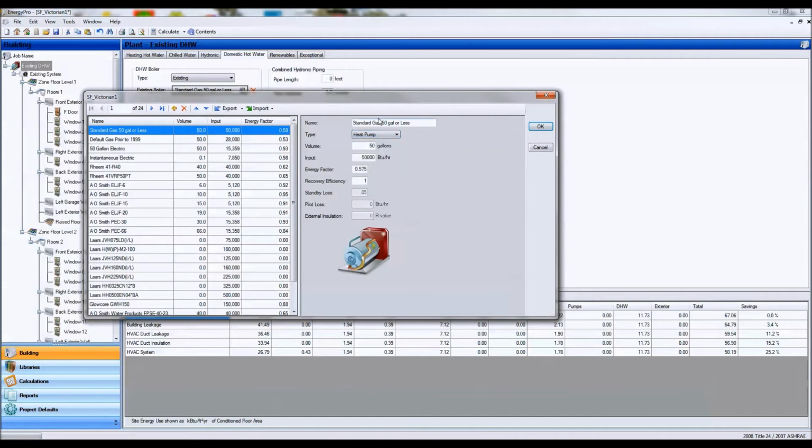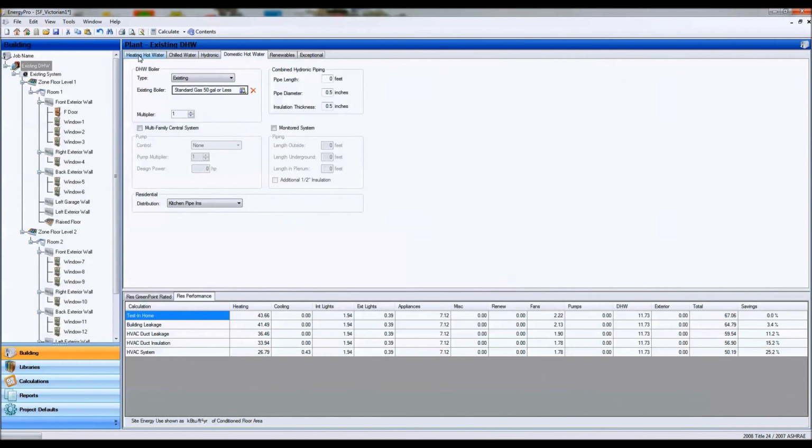And your heat pump water heaters, if you do have one, will have an energy factor. This is very similar to the COP, or the coefficient of performance. Okay, that you'll also see with the gas-fired some tankless water heaters. These will have a 0 volume and a real high output. Okay, and you'll see real high efficiencies as well. Some of them have some lower efficiencies. That's if they're not self-condensing tankless water heaters. So that pretty much wraps up the domestic hot water systems, if they're tanked or not tanked.